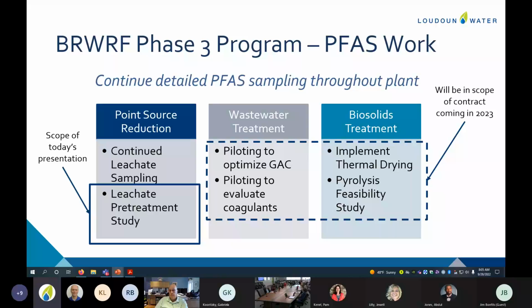No, we do not. So we are doing anaerobic digestion, just followed by dewatering. And I would say very few facilities nationwide are utilizing thermal drying because the technology is expensive and it doesn't scale down well. So to date, Broad Run was too small of a wastewater treatment plant for that technology to make sense.